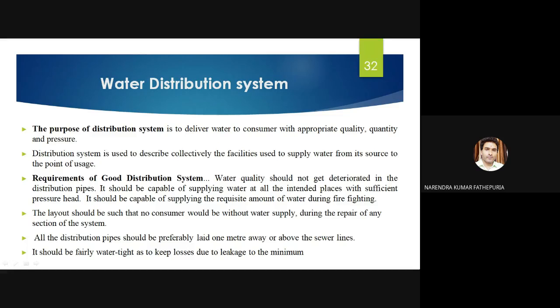And the quality aspect of water, you should not compromise with the quality. The treated water sample you have to take on a daily basis and you have to check all the parameters, physical, chemical, and biological parameters. Testing laboratory will be there. You have to check pH, turbidity, taste, odor, color, as well as the pathogens also, the MPN test, you have to do that.